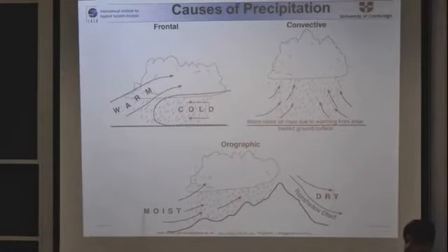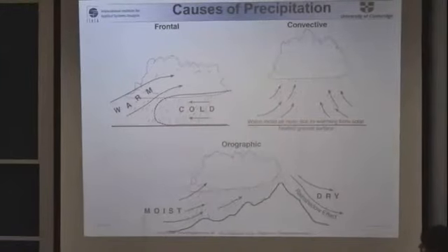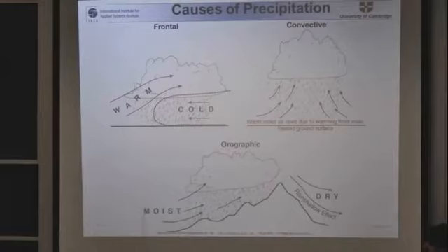So evaporation goes up, and that produces convective precipitation. The third type is orographic, when air masses are forced to travel upslope. That is produced mostly in mountainous regions, like in our northern Pakistan. The frontal type produces a lot of intensive rainfall, while the other is not intensive but prolonged precipitation, like we had a couple of days ago here in Lahore and overall Pakistan.